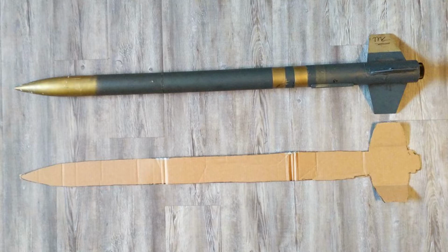First, a projection of the silhouette of the rocket was cut out onto a flat piece of cardboard. This was used because the center of pressure is approximately at the point where the surface area is balanced on either side. So a piece of cardboard or paper balanced at a point would show the center of pressure if the mass is negligible. The cardboard cutout was balanced on the same string, and the center of pressure was found to be 21.1 inches away from the motor retainer.